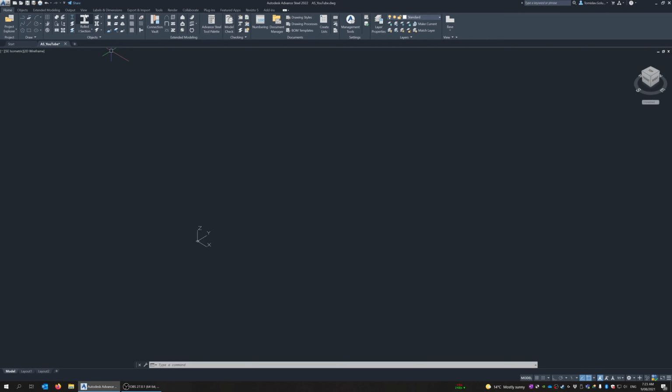So the main one you're going to be playing with is this rolled I section button up the top here. If you click on the down arrow where the words rolled I section are, there's a little bit of a flyout, and it'll present itself with all the other different sections, and if you hover your mouse over it, it comes up with all the other sections. So if I want to do CHSs, flats, round bars, squares, channels, or PFCs, I can do that here, but rolled I section covers the majority of the members. So if you click on the actual shape, you start that command.